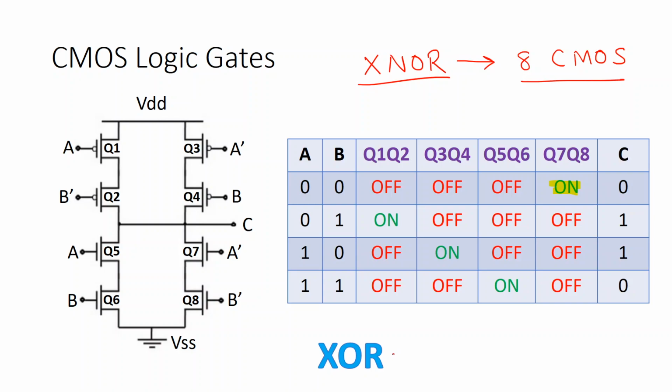If you know this already, and if you express XOR as AB dashed plus A dashed B and then look at this circuit, and knowing that XNOR is AB plus A dashed B dashed, now I have given you enough hint actually. Now you will be able to directly see where you have to put your A dashed B dashed and where you have to put your bubbled gates. So this is left for you as an exercise, and probably I will also give it in the tutorial, but you practice this for your own sake.